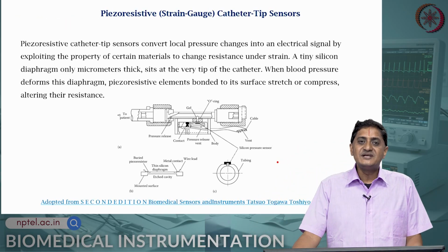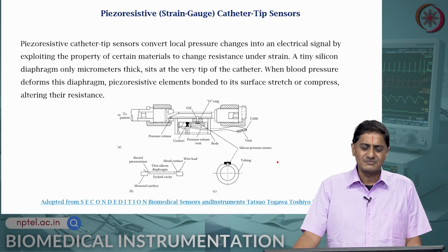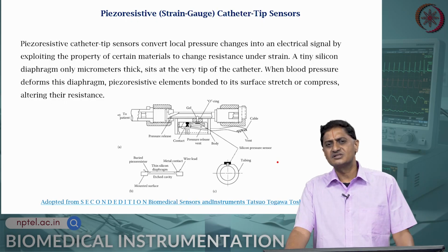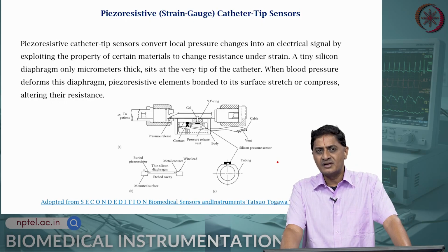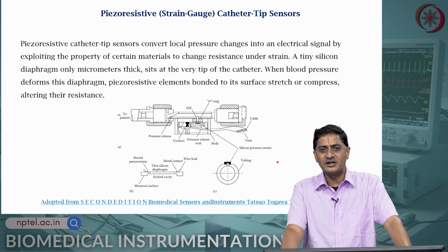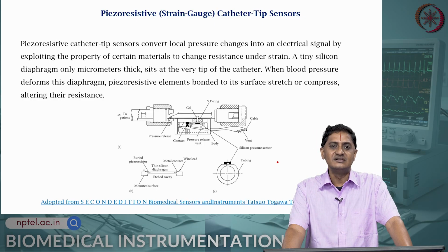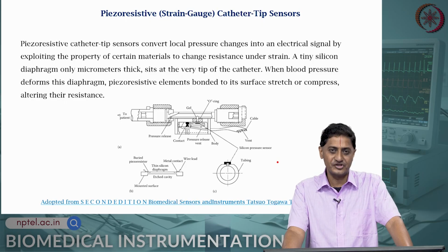First of all, what is piezoresistivity? We have heard of piezoelectricity. Piezoelectricity essentially refers to the phenomenon wherein when a force is applied onto some specific material, it generates a charge or an electric field, a change in the charge or an electric field, thus reflected as a voltage.